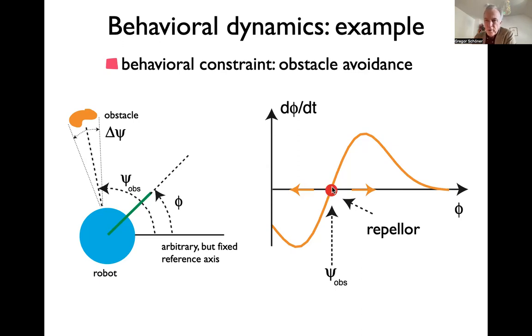Well, obstacle avoidance will be just one contribution to the dynamics. You will have, for instance, also attraction to the target, and if the obstacle is far enough, it will be a small contribution, and the target contribution might dominate, and that might push you to cross this boundary where there's a jump in the heading direction. So we need to have a dynamical system that has really a continuous right-hand side, the forcing function being continuous, to guarantee that we get the properties of the dynamical system: smooth, continuous, differentiable time courses. So that's where we end up going through 0, where we make a decision.